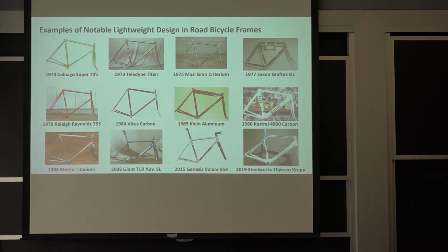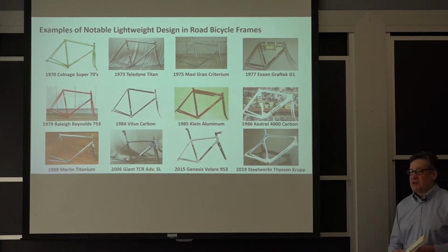TRIP steels are steels that go through a martensitic phase transformation, which gives them better strain to failure. Are you guys familiar with that at all, TRIP steels? Transformation-induced plasticity. It's a way that you can increase the strength, or you can increase the elongation of a steel without increasing the work hardening rate. Actually, you can have a much lower work hardening rate, so you can deform much further before the part breaks. So what I was trying to get them to do was a hydroformed part.